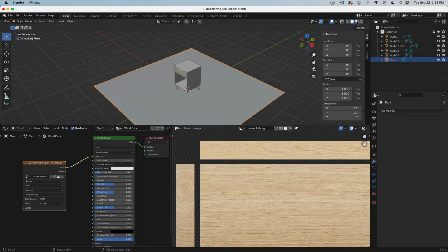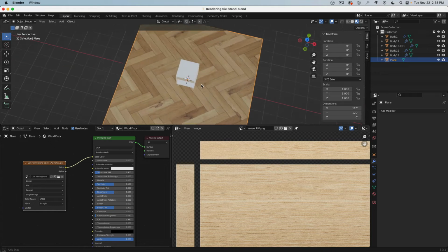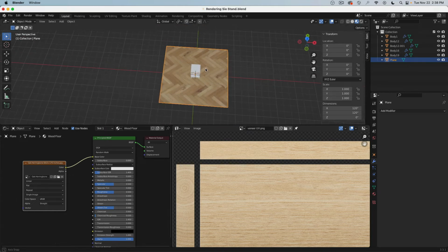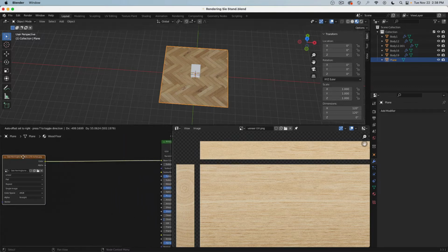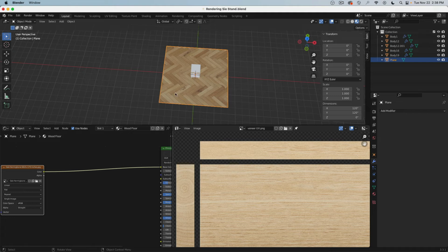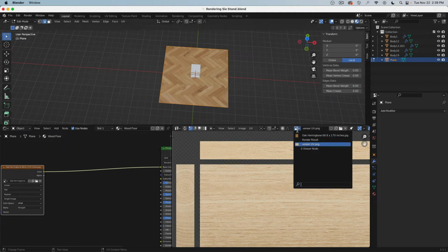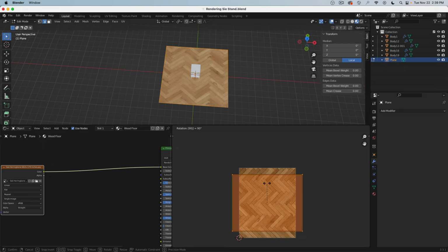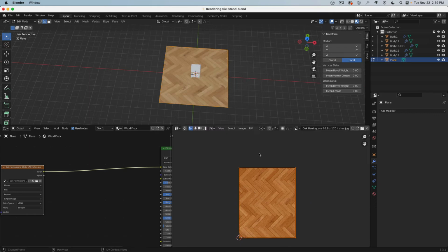Then we can go to UV texturing. There we are. Looks kind of okay. Very good. Maybe it does not have the rotation I need. So there are 2 ways to do this. If I go to edit mode, open here this geometry, press A to select the rectangle, I can press R and 90 and rotate it. And you see how this adjusts everything.